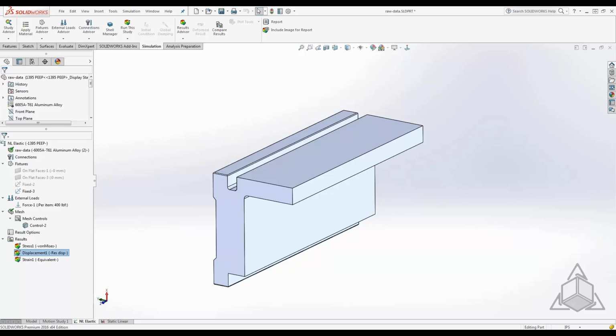In a nonlinear analysis, your stress will follow that wall. It will stay normal to the wall as it deforms. That makes a huge difference. In a linear static analysis, the force is instantaneous. So basically the force is applied, and if it's applied in the normal direction, basically normal to the face, it's just going to go in this direction.